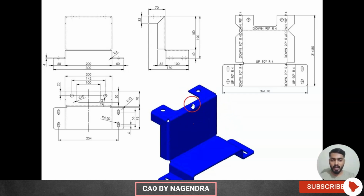Here we have the isometric view, then the front view, then the top view. Beside the front view we have the right side view. If you are looking from here, this is the left side view. With the front view, the top view at the bottom and the side view on the left, this is first angle of projection. In first angle of projection, the left side view will be on the right side, as we already know. Then this one is the flattened view, like an unfolded view.